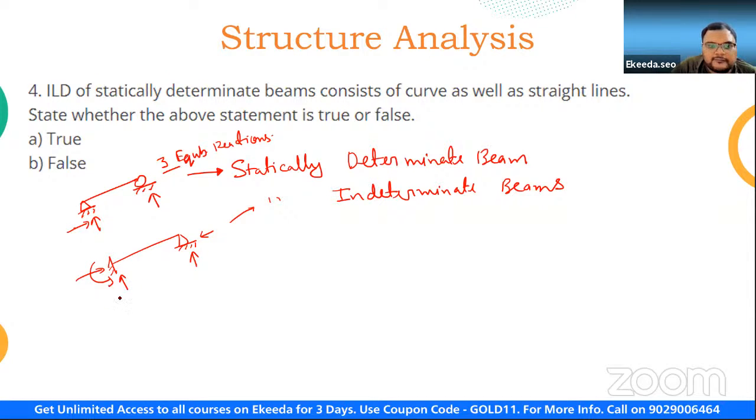Now we have a total of 3 plus 2, so 5 reactions, but we have only 3 equilibrium equations. So what will happen? We have more unknowns but fewer equations to solve them. So we say that this beam is a statically indeterminate beam. Now what it is saying is that the ILD of a statically determinate beam consists of...